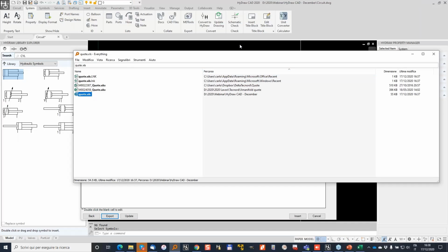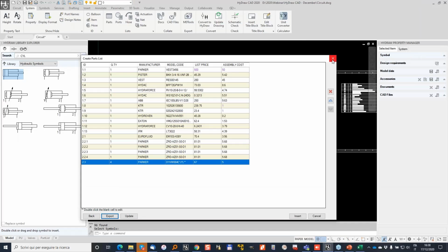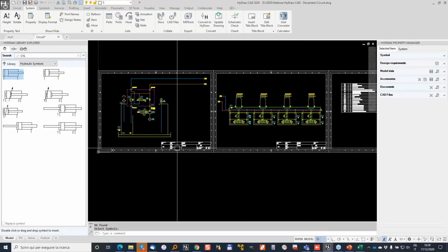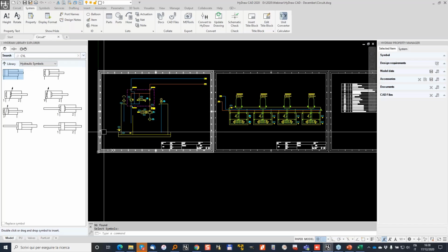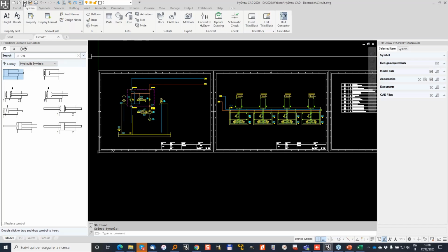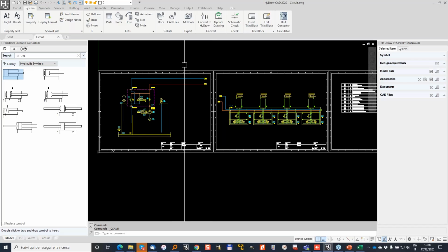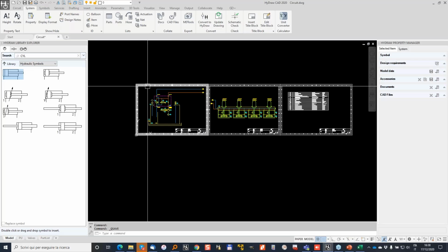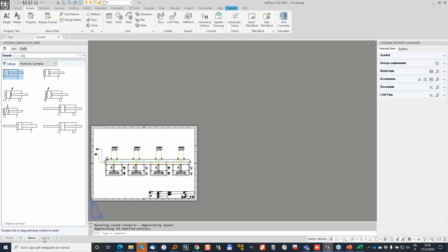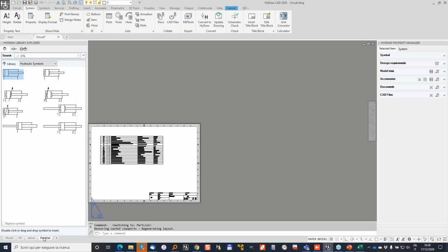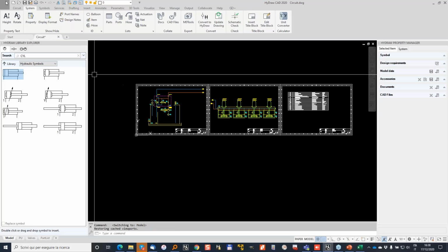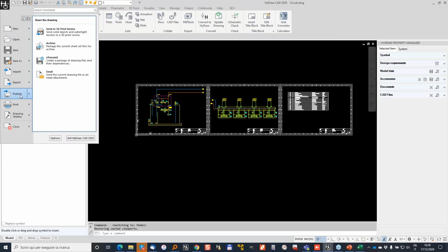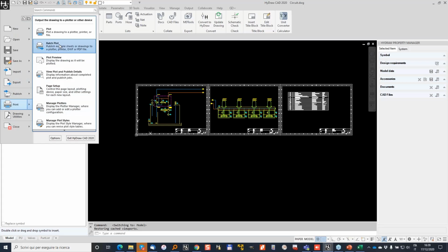Then we need also to give the diagram to our customer. Together with the part list, we want also to give the diagram. So since we started with a good template, now I want to publish it into a PDF. So let me save my diagram. So if you wanted to publish 3 pages, like in this case 3 layouts, directly in one document, the good way is to use the publish option. Well, you can use the print batch plot.